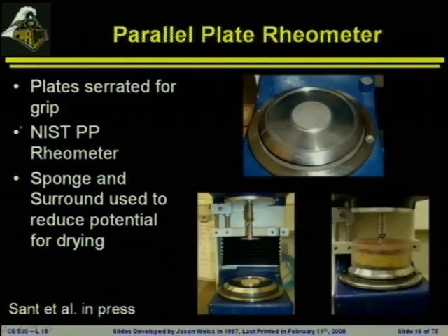This was some work that we had done with Clarissa Ferraris at NIST. So this is the NIST rheometer. Here you can see that it's a parallel plate. Here's the upper plate. Here's the lower plate toward the bottom. And the plate actually has some serrations on it. So it's basically got like a crisscross French fry type cut on the surface, so it can sort of grab